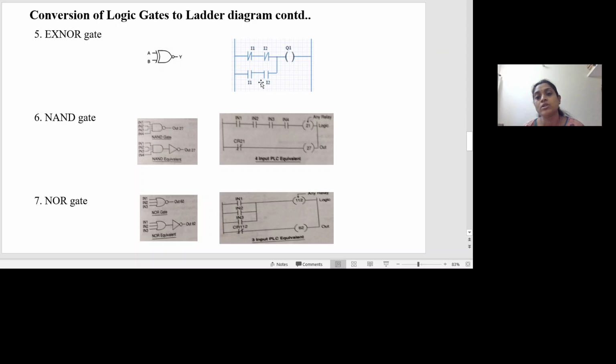An AND operation means it has two inputs, and those two inputs are to be connected in series. Similarly, we have one more AND operation between the variables A bar and B bar. That AND operation is also represented as two contacts in series. These two terms are ORed together, so in between we have a plus, which indicates an OR operation.